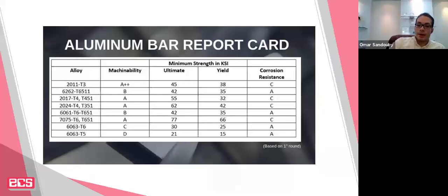In metal, and I believe many of you are aware that in aluminium, for instance, or steel or titanium, you get different grades of alloys. Aluminium is not just one single alloy. So for instance, if we were to take like the 7000 series, you can see here the tensile strength and the ultimate strength is maybe almost double that of the 2000 series or the 6000 series.